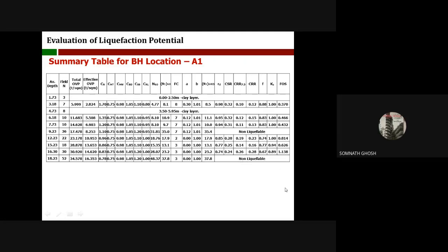That means when we calculate the carrying capacity of a pile, these two layers are to be omitted. That means you have to consider that these layers are not providing any skin friction, and you have to just omit these two layers. You can't consider the effect of these two layers because you don't have any data on the value of skin friction and all.